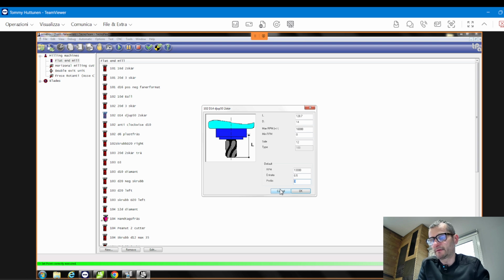For example, if I buy a tool where the maximum speed is, for example, 5,000 RPM, because more is very dangerous for me, I don't know, and I put 18,000, I damage the machine and maybe also the person behind the machine. Okay. So it's very important to understand what we are doing. We are working with a machine, so for sure you must clarify, if it's not clear, what you are putting in the machine.